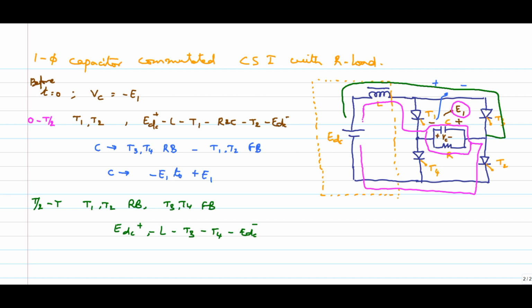T3, through capacitor, after that T4 and back to supply. Okay, this direction is also there through resistor. So this is the way it is going ahead. Now let me consider load. Let me consider the voltage across load. This is my resistance, and if I take plus and minus and V0 from 0 to T by 2, what will happen? It is positive in nature.